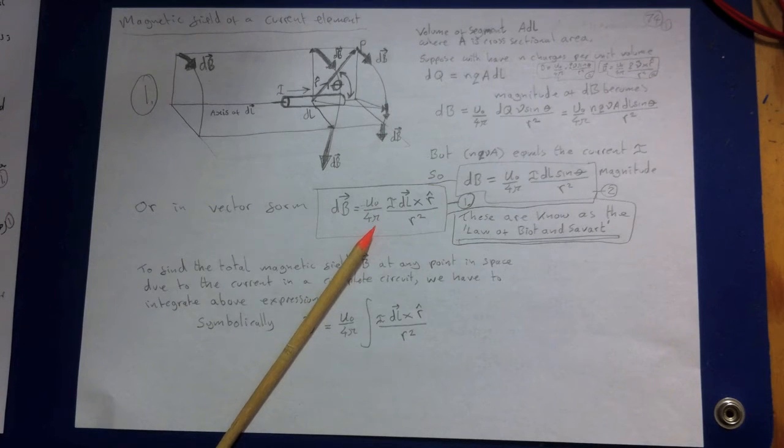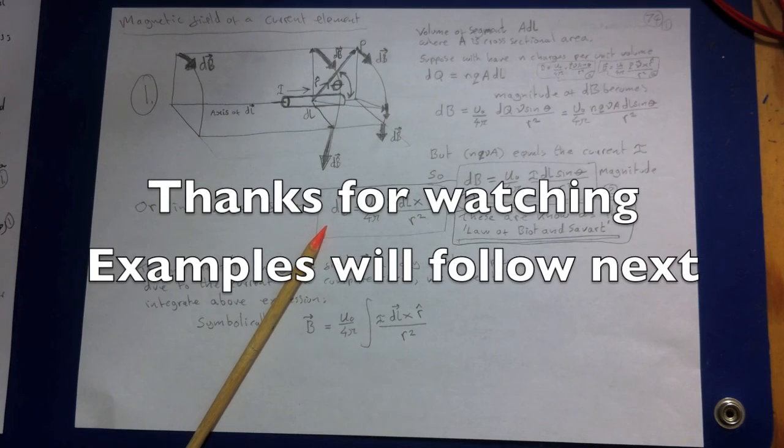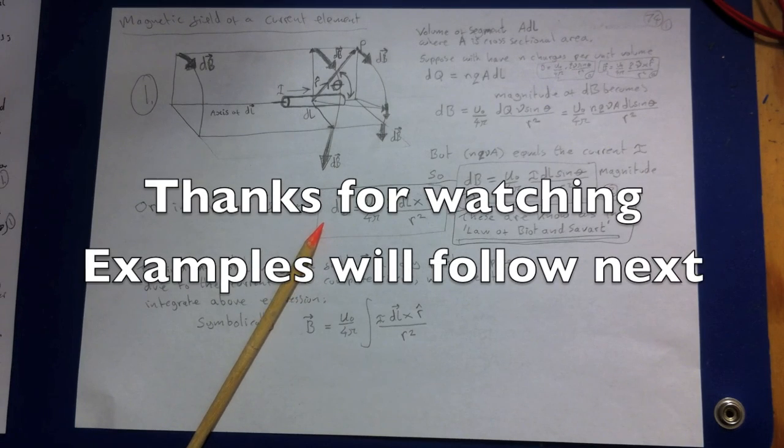If matter is present in the space around a conductor, the field at any field point P in its vicinity will have an additional contribution resulting from the magnetization of the material. We'll return to this point later. Unless the material is iron or some other ferromagnetic material, however, the additional field is so small that it's usually negligible.